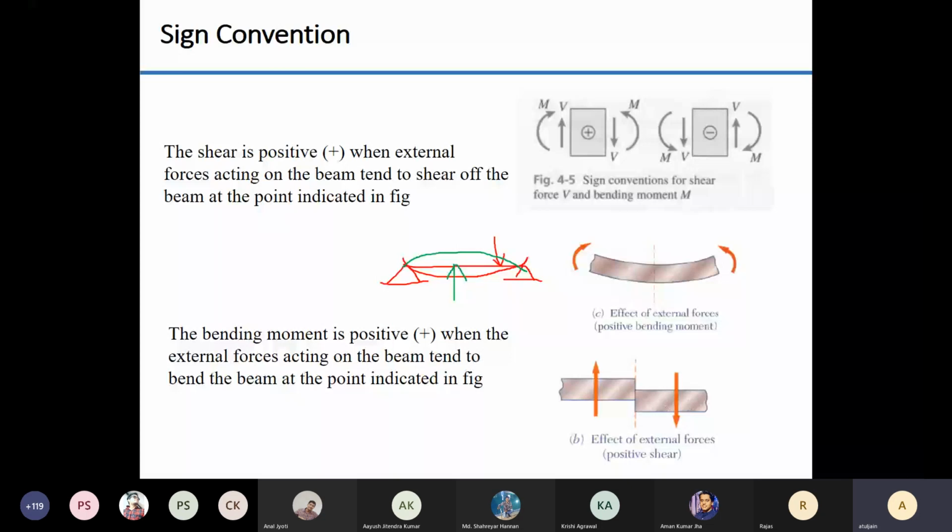So whenever you solve any problem, my suggestion is draw this in the top right hand side of the paper that you are solving, so that you don't make any mistake in the sign convention. The only place where you can make a mistake in this very simple problem sheet is in the sign convention. If you understand the sign convention and you know how to draw free body diagrams, this problem sheet is done. Nothing else is needed. Clear?